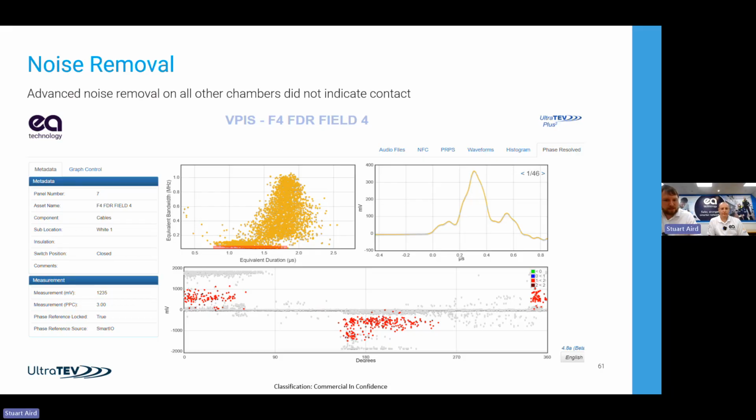So what do we actually find? It's not just data. When you move on to the next page, what you'll see is lightning arresters. That gives you an idea of the region this came from, in terms of the terminology. The lightning arresters were loose and able to move freely on the back of these T-boots, which is never a good thing. In this instance, the particular bolt that was holding those on, you can see this pushing bolt has started to eat away, and there's damage around the boot itself.